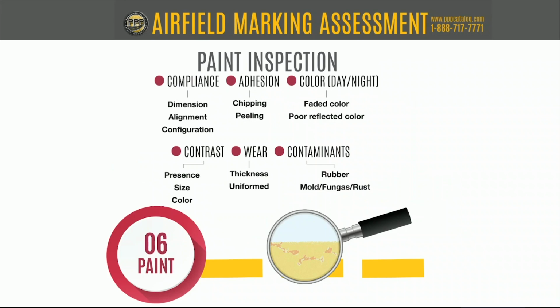In the airfield system, yellow means that you're on one part of the airfield, and white means you're on another part. To get those confused, especially on smaller civil aviation issues, or where people are flying in that aren't familiar with your airport, it could be a dangerous situation. So definitely watch that retroreflective color. And I know your instrument, Mike, actually the mobile instrument and the handheld both measure that nighttime color. So I think that's really a good addition to anyone's assessment.